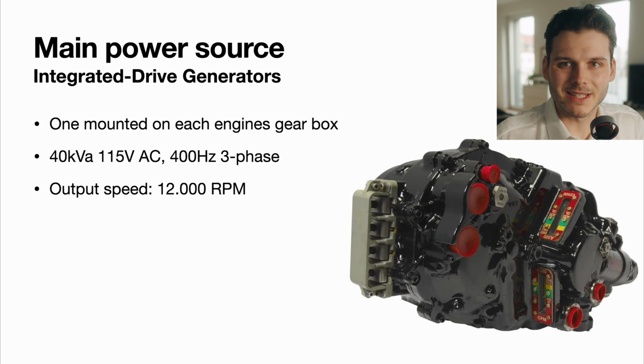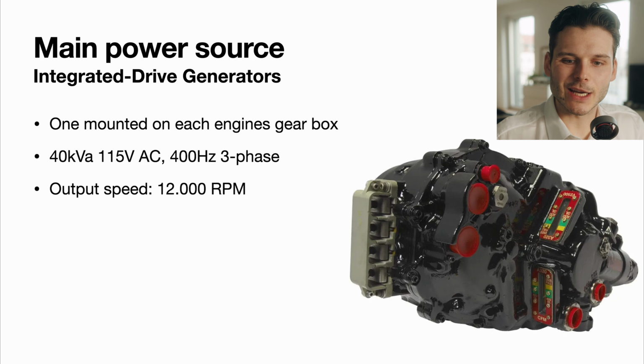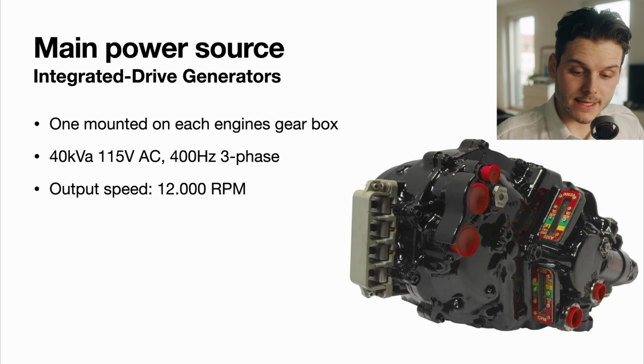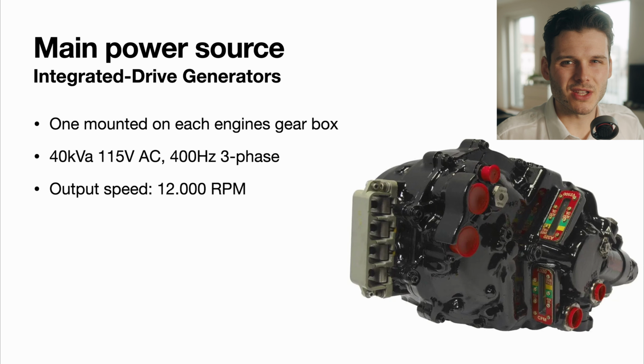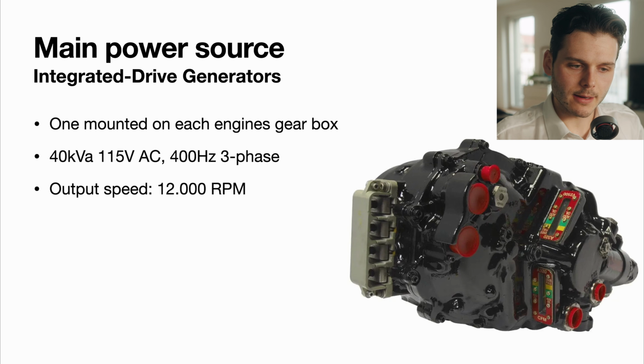Of course, the gearbox has variable speed, and that variable speed, depending on the N1 rotation speed, is then converted to a constant speed via hydromechanical means, kind of like those weird gearboxes in some automatic transmission cars. I think it's called CVT. I think it's comparable to that actually. And if broken in flight, we can actually still fly. It's a MEL release. I think it has to be repaired within 2 days of it being broken, but we can still fly with it.